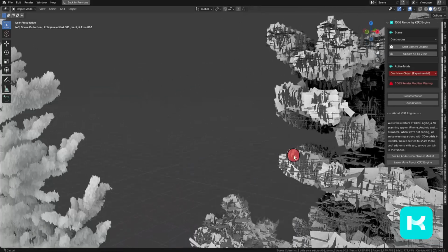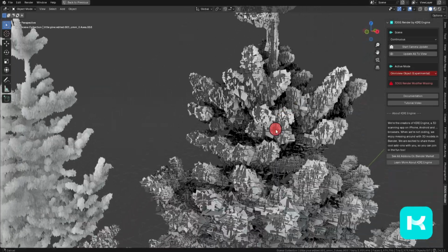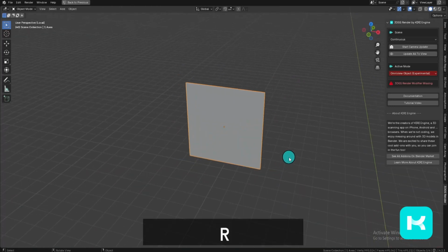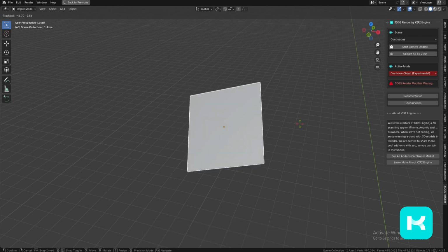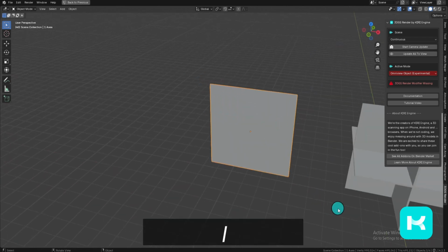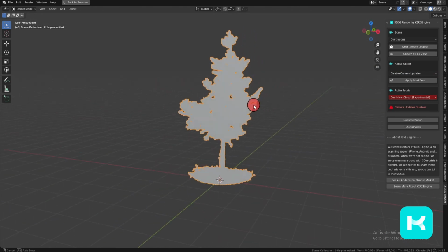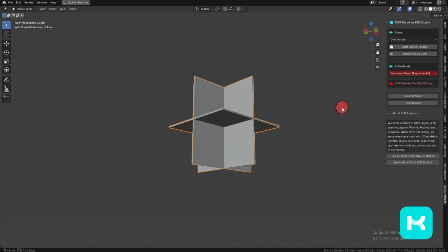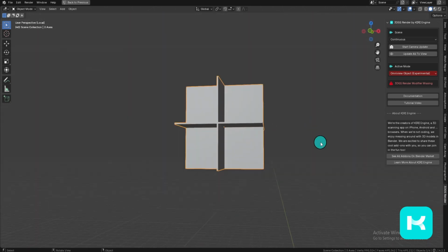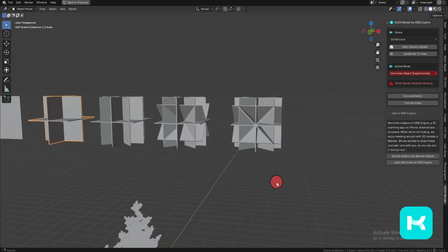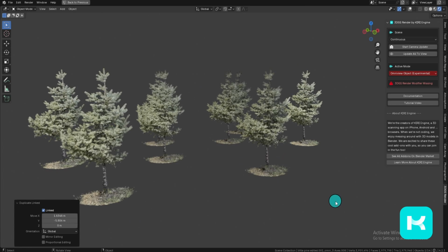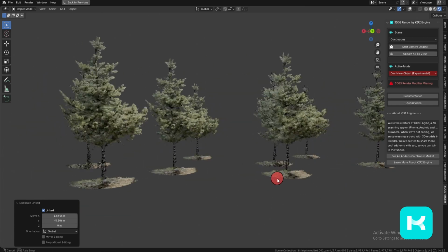Omniview Object. If you are familiar with the concept of imposters in video games, this is a similar experimental approach. The standard 3dgs objects have one face per 3dgs point, and this face rotates to the current view. An Omniview object has multiple faces per point. Each face is static, does not rotate, and faces permanently aligned to a specific axis. These objects don't need updating and can be instanced, making some performance-heavy tasks much lighter.